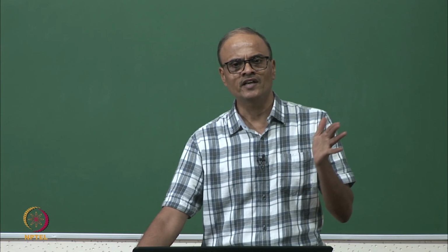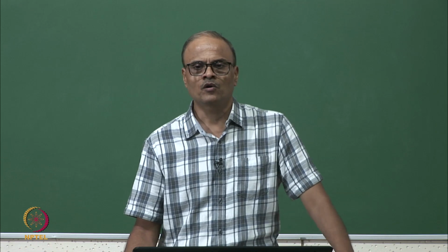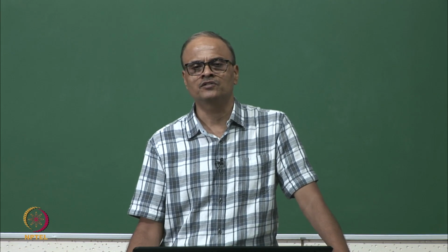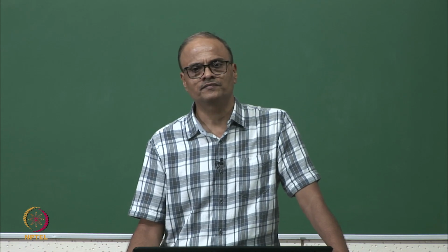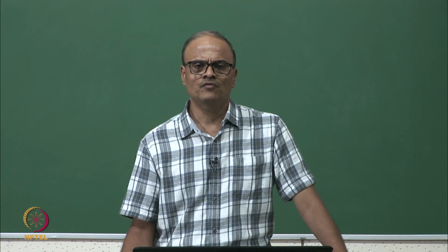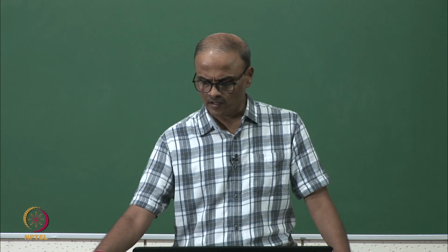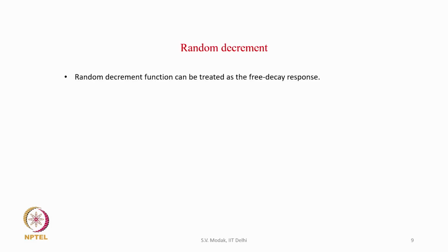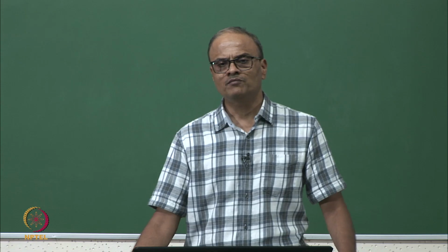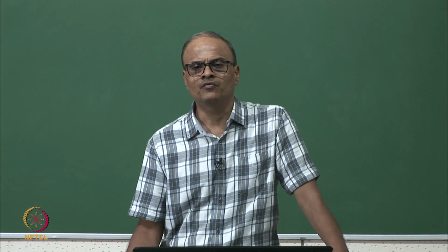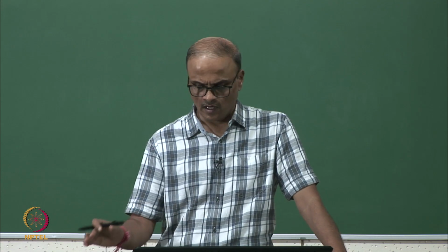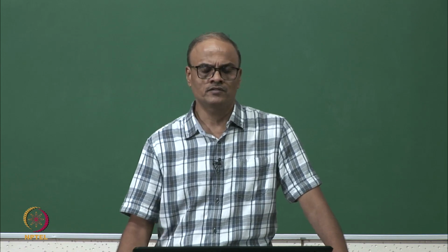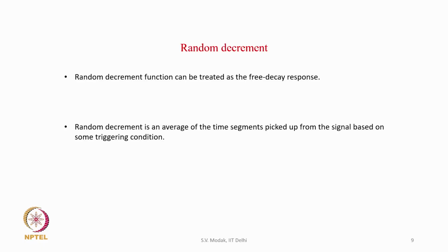Free vibration response decays with time due to the presence of damping, and the correlation functions also consist of damped sinusoids. So, correlation functions are also like free decays. Let us briefly look at what random decrement is. Random decrement can also be treated as a free decay response. The concept of random decrement was introduced to find the free decay response from a random vibration response, and random decrement is an average of the time segments picked up from the signal based on some triggering condition.